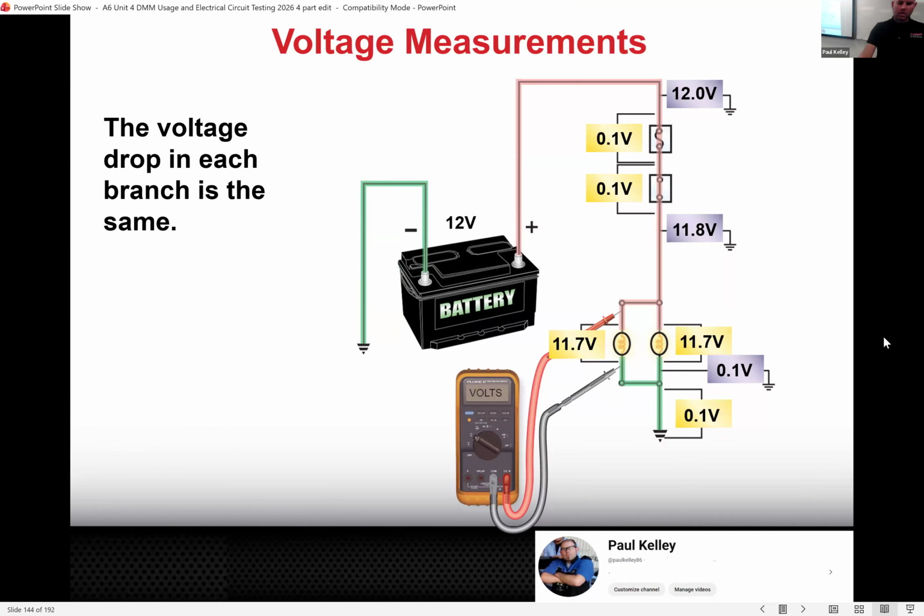Honestly, on this diagram, you can't spend more than an hour diagnosing this. There's something wrong. Cool, but sometimes the problems are kind of crazy, and it'd be a much more complex one. And you might say, hey, I spent an hour, I need more time. You should be able to say, here's what I measured and here's what I can tell you is not the problem. But I'm still trying to determine, I've got to check individual things. Is it this harness? Is it this fuse? Is it this switch? Is it this wire? Is it this splice? Is it this bulb, that ground?